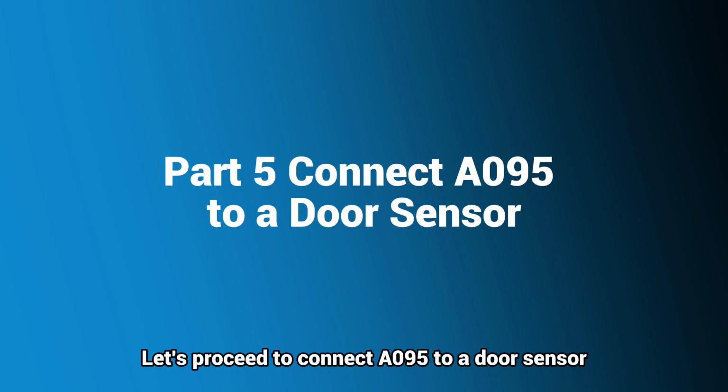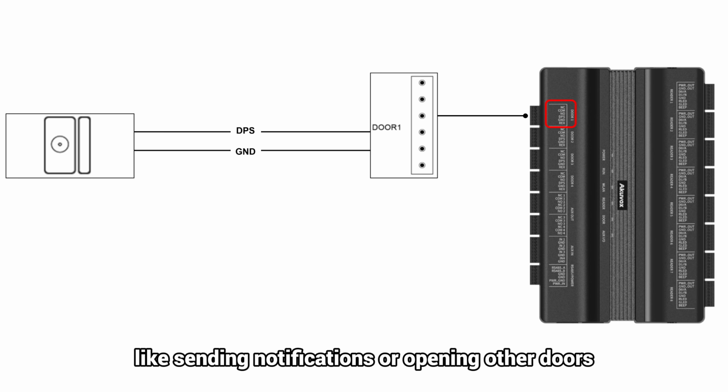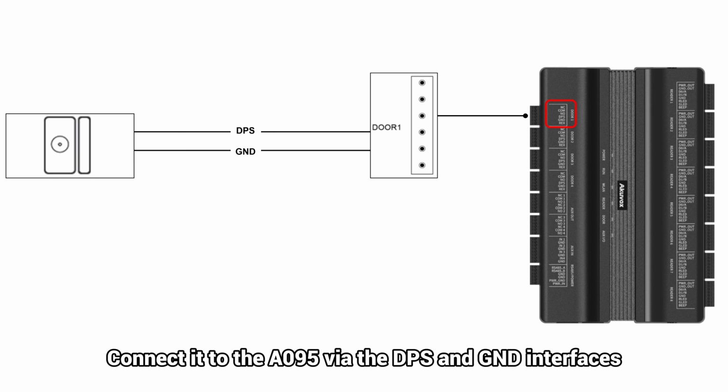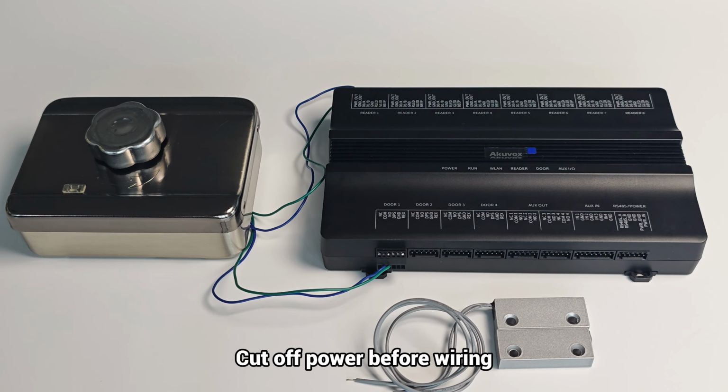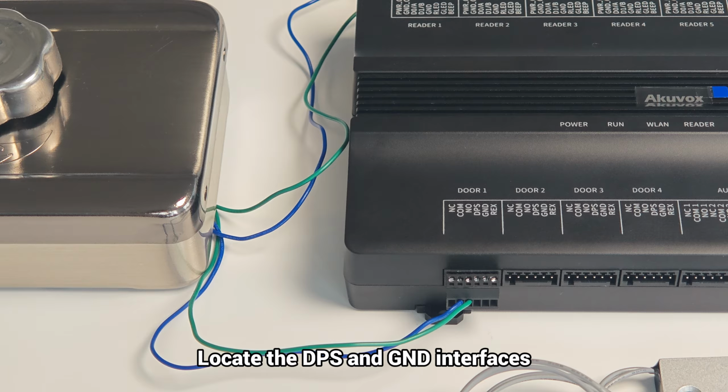Let's proceed to connect A095 to a door sensor. The door sensor or door position switch detects whether the door is forcibly opened and trigger actions, like sending notifications or opening other doors. Connect it to the A095 via the DPS and GND interfaces. Cut off power before wiring. Locate the DPS and GND interfaces.